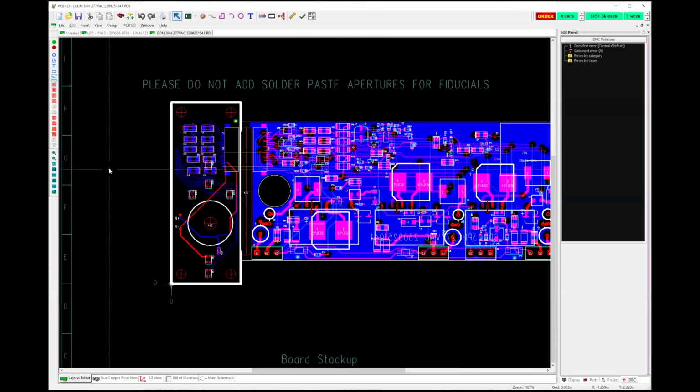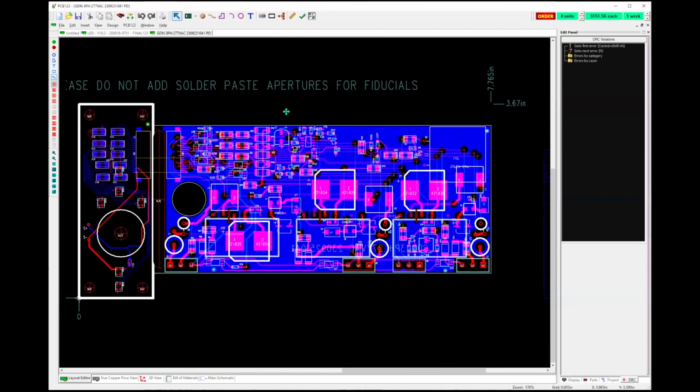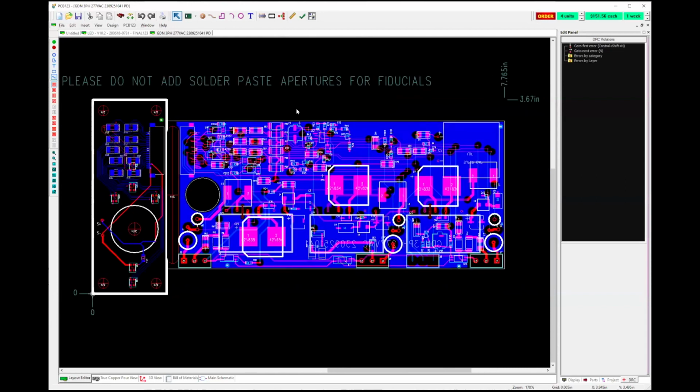So again, when you're making your board, you can make your own parts. It's not hard. It does take some practice. You need to know the rules around manufacturability. Pad sizes in relation to the actual physical part, that sort of thing. Spacing rules, all of that. It's something that you learn as you work over the years. You get better at it to the point that the math just is in your head.